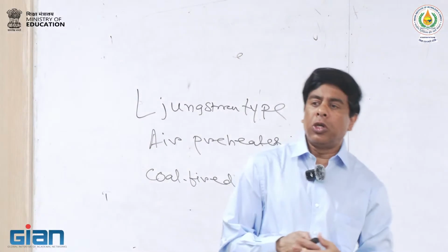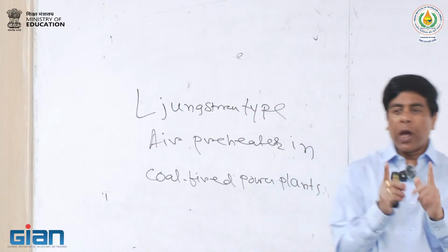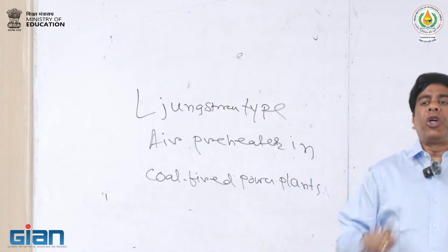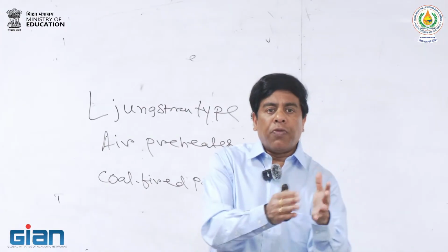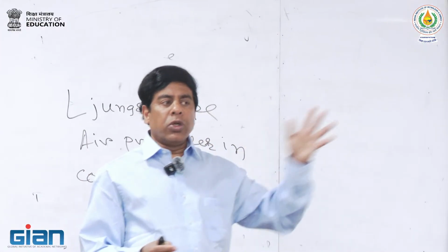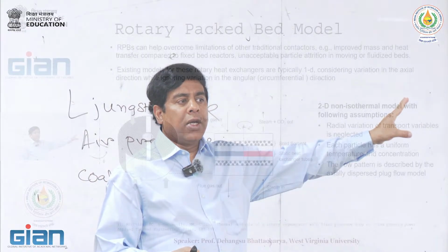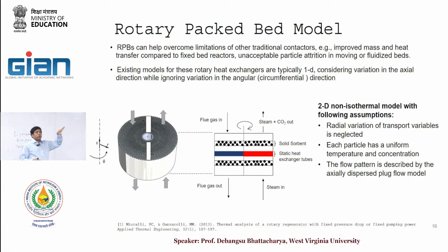And if you look into a power plant air preheater, there are 3 sections. There are also some cases with 2, but most modern ones have got 3 sections. So primary, secondary, and tertiary air, and you could have the different air preheater sections. That way you can segment it, and these guys have come up with their seal design and all of that to ensure that there is no leakage there.